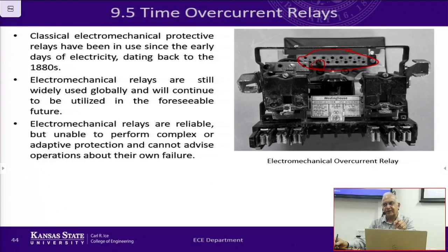So you have 4 to 12 amps. Wherever you put the plug, that becomes your tap setting. This is with limited selection of tap values, but with digital relays you can pick anything you want. You can pick 4.1, 1.1, 1.2, 1.3, it is almost continuous.